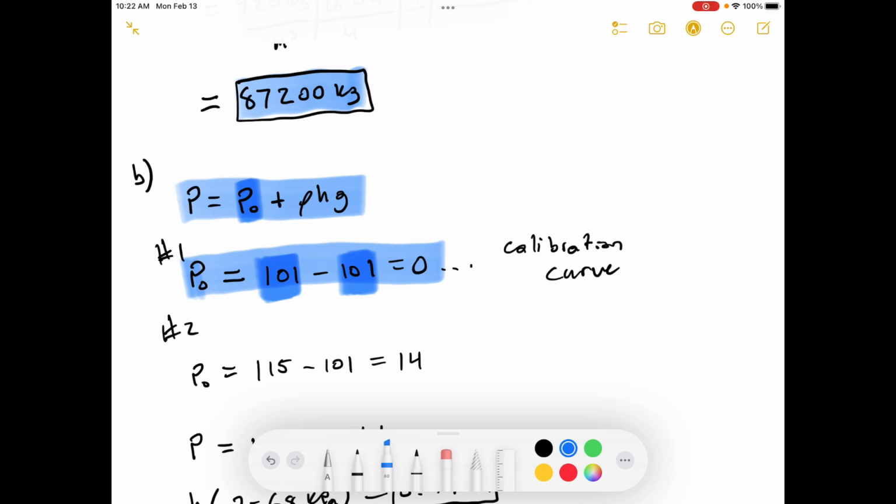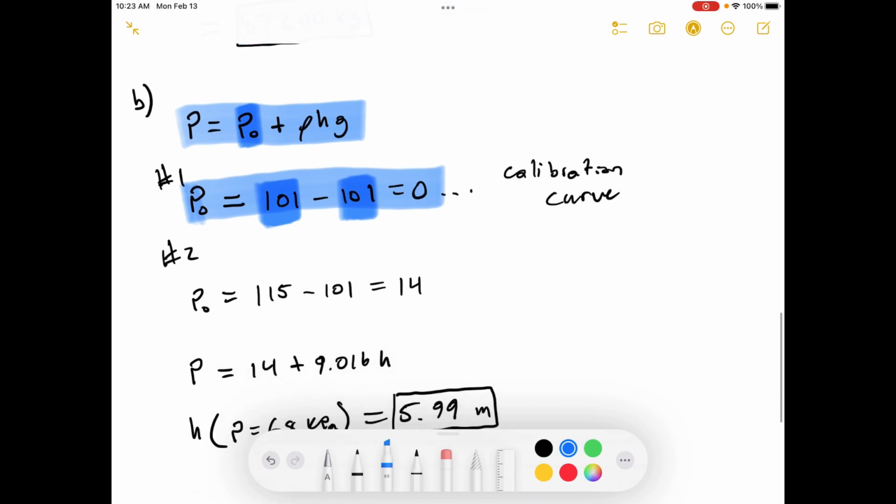So that's going to make the pressure in the tank seem artificially higher than what it actually is, just due to the liquid. So this pressure is actually higher than what it should be, and so when we run our calibration and we subtract off our atmosphere off of that, we actually end up with a little bit of extra pressure that's affecting our system.